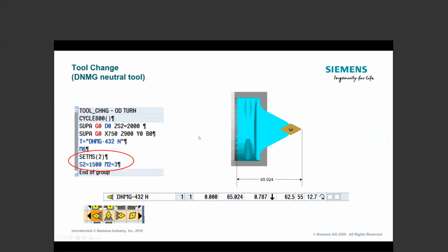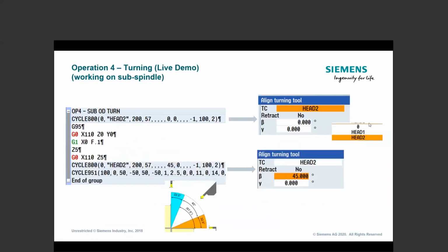And then we're going to go grab a neutral tool. So here I can jump in, we can grab a neutral tool and change some orientation angles, and we can fool around with that. So we're now going to set our main spindle to the counter spindle. That's going to drive the counter spindle as my main spindle. And we can play around with those different orientation scenarios. So if we look at it, boom, jump back in.